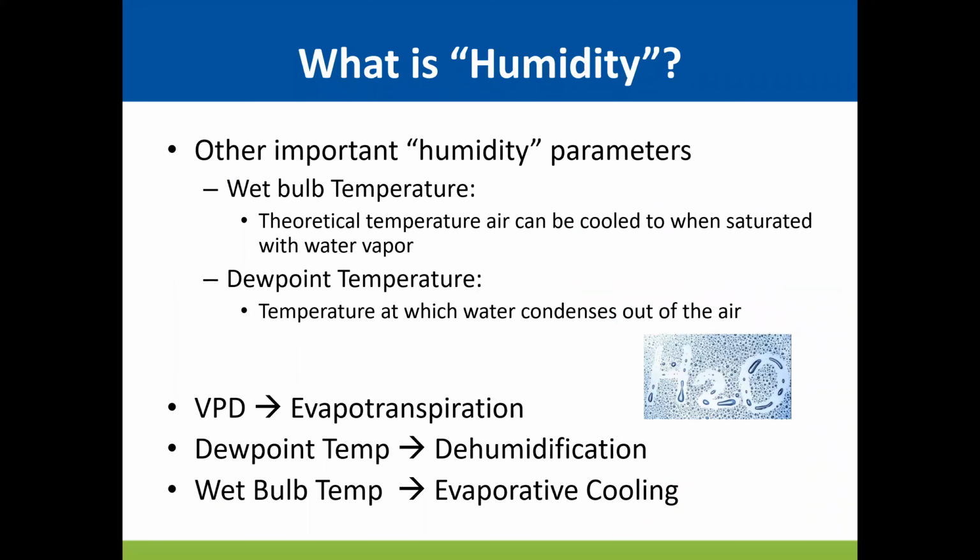Now, I'm going to come back to that in a second. Other important humidity parameters that all of us should be aware of are, one, wet bulb temperature. This is the theoretical temperature at which air can be cooled to saturation when we add water vapor to it. This is the process of evaporative cooling. The dew point temperature is the temperature at which water condenses out of the air.